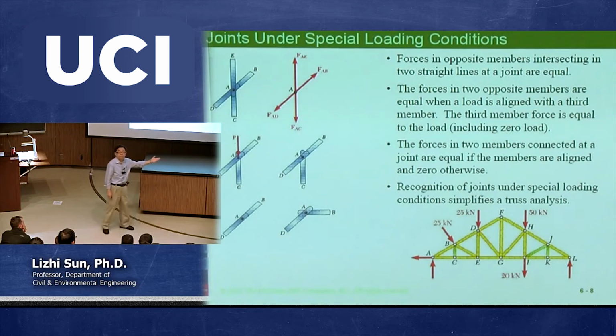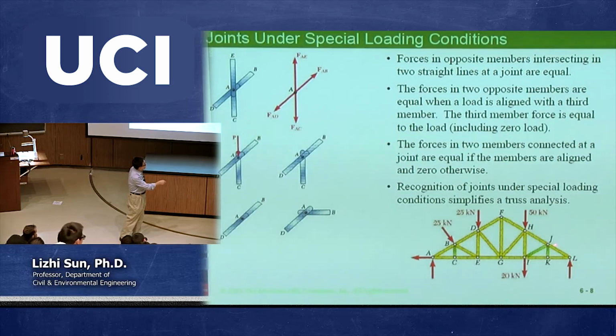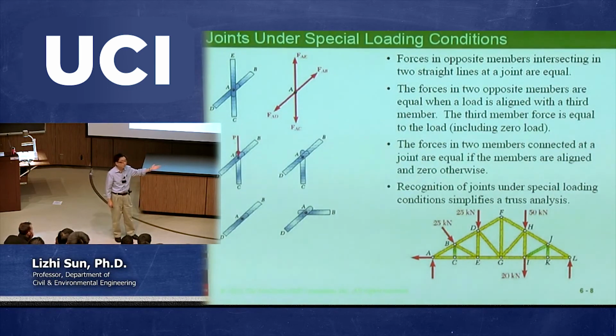Let's say 0. So do not use the concept of 4 members at this time, because one of the members in fact equals 0 because of another joint. So then I can conclude Fij should have a 0 force. The same thing, this J is in fact kind of 3 members connected in terms of force, and 2 of them in one direction, then the third one must be 0 in terms of force. I'm not saying there are no members. There is still a member made of wood there. But I'm talking about force. The force equals 0.